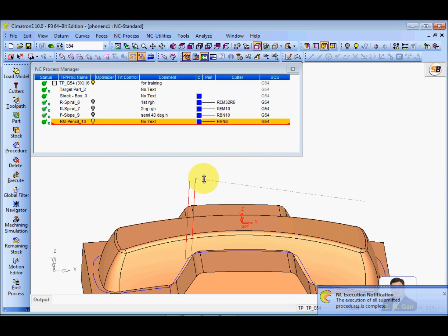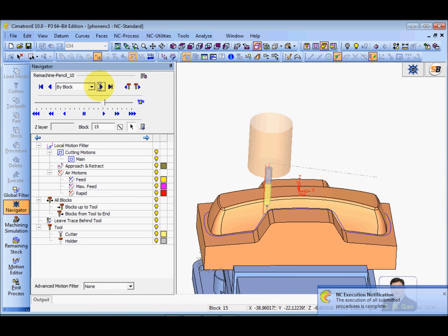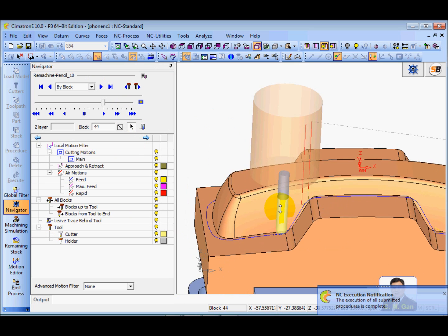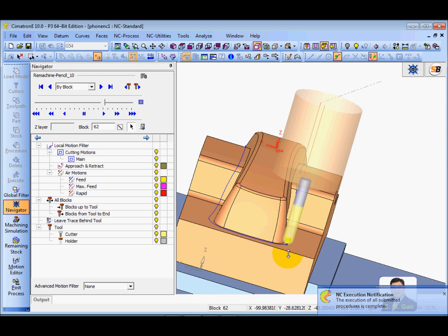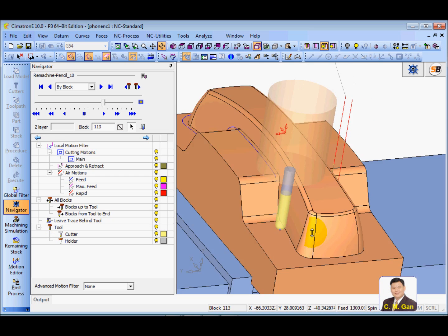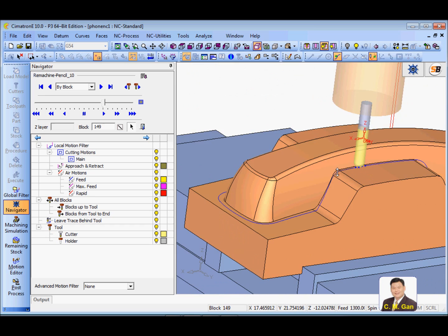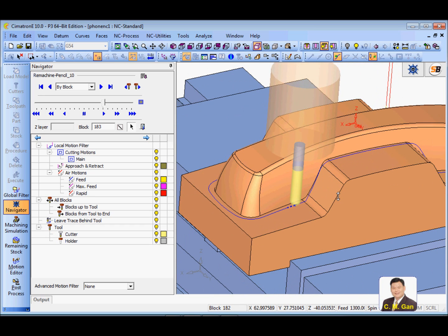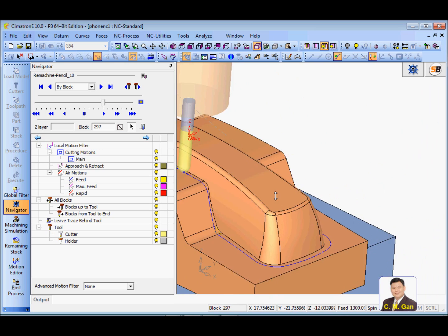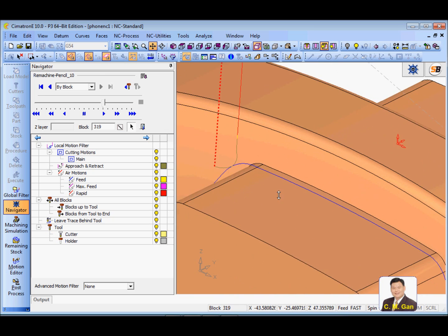Let's go to the navigator and check. You will cut the corner one time. Of course, this one also with a surface offset of 1 mm. Cut the corner one time to remove the excess material at the corner, so that the finishing cutter will not vibrate and will last longer. So this is one pass.